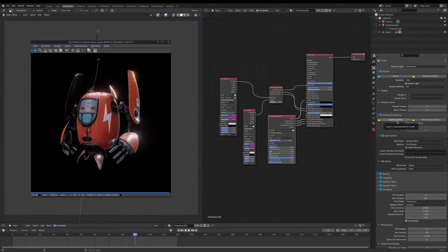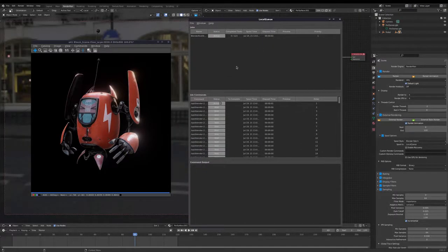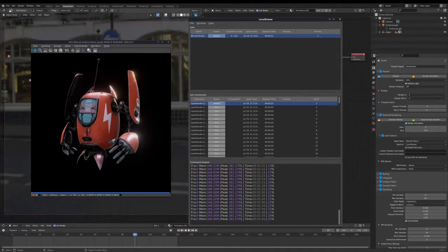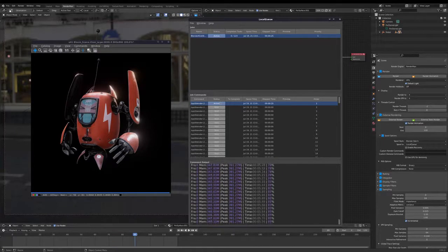This is how you render out your animations. So again, if I wanted to render out these 128 frames, which you can see on the screen now, I click the render animation button, and then I click external renderer. And what this does, if I fire this up, is it then starts this thing called RenderMan's local queue. And if I then come through each one, you can see the progress of what it's actually doing. So it's actually now starting to render out all of my frames.